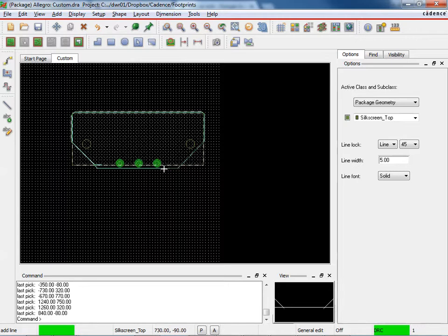Now when I do these lines normally on parts, I actually go through and do all the measurements and everything of that nature and then use the command line. And the way you can do that, just as a side note, I'll show you here. I've got a line selected and I'm going to say X. I'm going to start at negative 1000, negative 1000, and then you can see I've got a line started now.